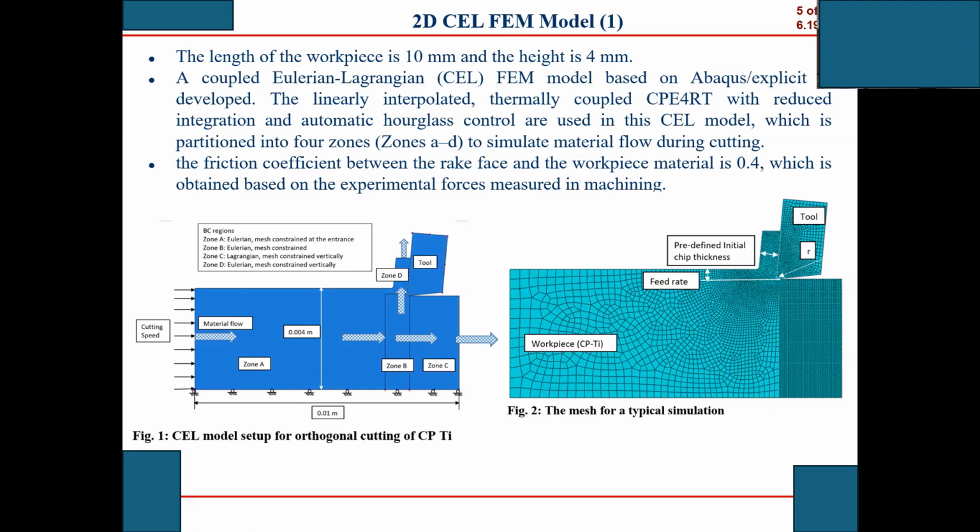However, Lagrangian means that the material points and the mesh are connected together, so as long as the material points are moving, the mesh will be moving. That's the reason Eulerian is very suitable to model water and fluids.